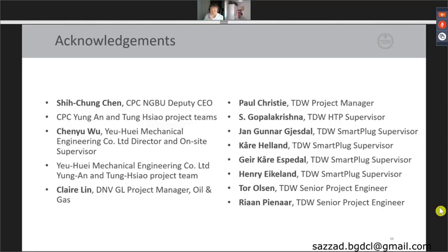The next question was from Mr. Zubri Rahman. What is the smallest and largest size for TDW smart plugs? Okay, the official range that we cover is 8-inch through to 48-inch diameter. But the reality is that the 8-inch was a bit of a special, so it's not typically being used elsewhere in other pipelines. So 10-inch through to 42-inch is the tools that we've actually used, but we do have 48-inch tools which have been developed and tested, but they've never been used in a 48-inch pipeline.